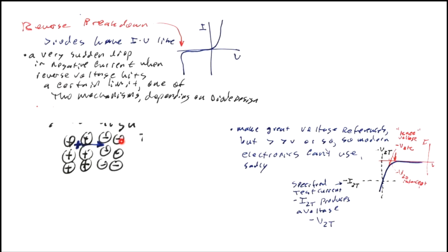So when this hole hits a silicon atom, an unionized silicon atom, it'll ionize it, creating an electron and a hole, and we'll get like twice the amount of current, or 30%, 70% more current, something like that, 66% more current. We'll get a bunch more current from that one collision. And if we have a huge field, then all those carriers get accelerated, and they'll go on and hit some more innocent silicon atoms, create some more carriers, and we get more and more current that avalanches or multiplies out very rapidly. But it only happens for a large negative field.